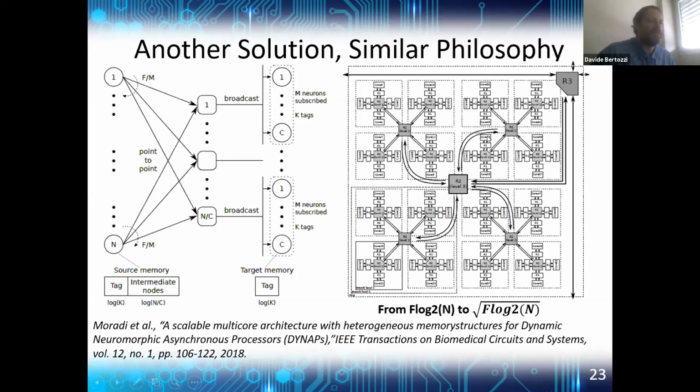Then you can have this level 2 router, and there can be actually multiple of them organized in a tree topology that actually deliver the intermediate routing options. So these intermediate blocks here. Overall, this adds up to a neurochip, and you can connect different neurochips together through a level 3 router. And for the level 3 connectivity, you have a mesh topology.